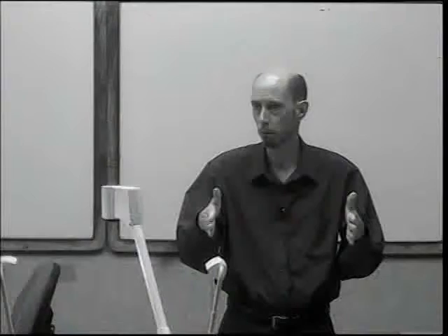Then you have to start thinking about the stuff we're talking about in this class. Then you need to use RF analysis. So, if a typical dimension in your circuit is larger than a 20th of a wavelength, then that's where we come in. That's what we're going to be learning in here. What do I mean by a typical dimension? Well, it may be like the size of your circuit board when you lay it out on the lab bench. That might be a typical dimension.